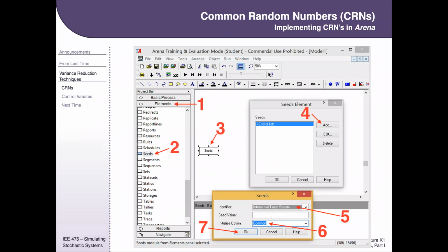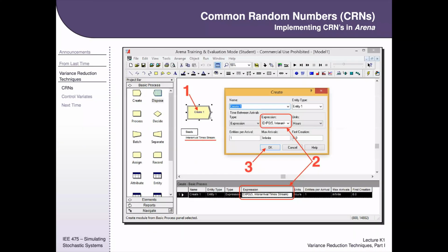So you can actually say, I want these 3 input models to use the same common random number stream, but everything else in my system can use different streams. And so that's something that you can do there. So the simplest thing to do is just to change this to 10, and then suddenly your whole system uses common random numbers. But if you're afraid, like, well, my system draws a lot more random numbers in the post-processing, not just in the input generation, then maybe I just want to make my input streams common random numbers, and that'll help guarantee that you get just the same customers, even though there's other random things going on in the rest of your system. So that's how you can do it in Arena,